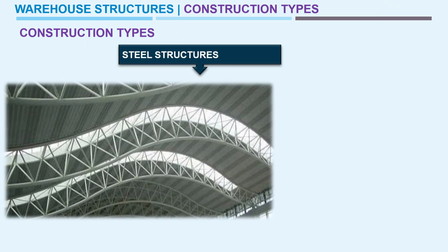And this is the fourth method, the steel grid structures. Generally these steel grid structures have a group of members which are connected at a single node. You can see here at the bottom chord various members are connected vertically and inclined. At this point you can see that four frame structure members are connected to a single node at the lower chord.